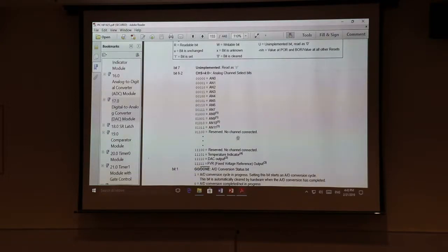Okay, so this DAC output here is only 5 bits, so it only has 32 different voltages it can display, which with proper filtering gives you not a very good signal, and certainly not good enough for any high fidelity audio. Normally we like to do 16 bits for high fidelity audio, so we're quite a few short.